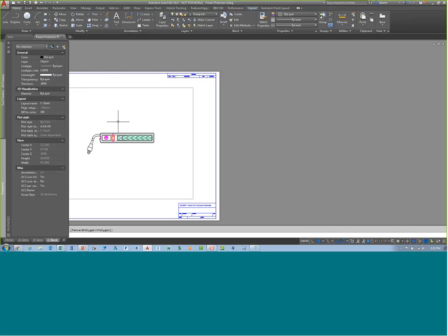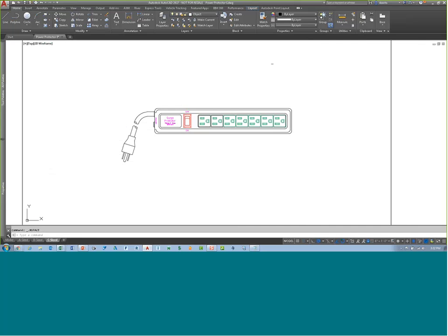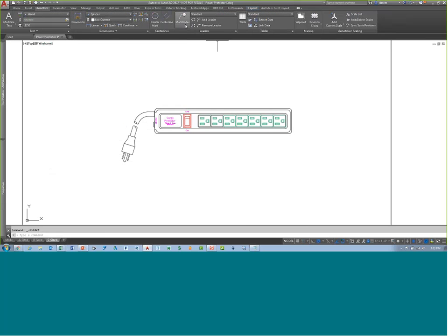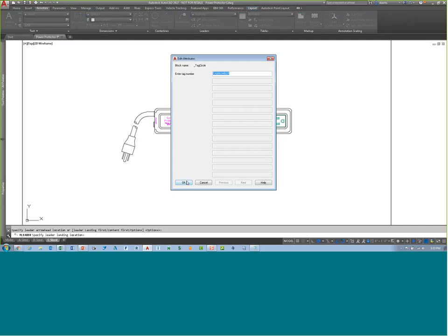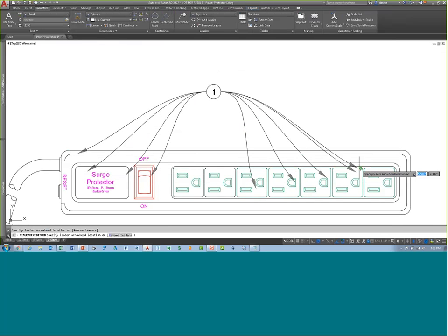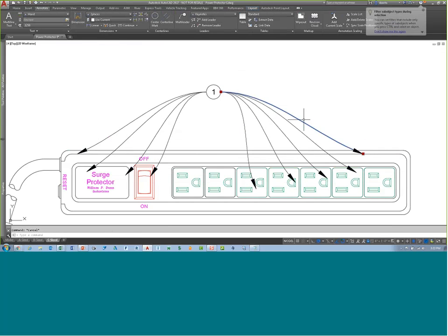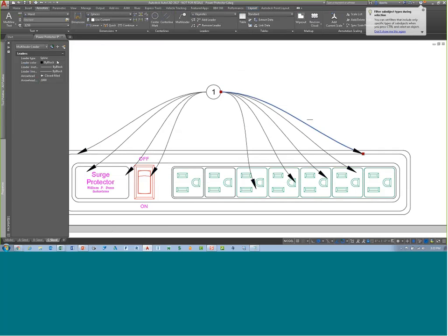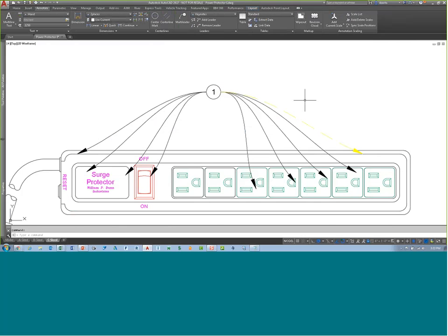Okay. So leaders. Creating leaders is not that hard. Annotate tab, leader commands. Pick the style that you want to work with. Hit multi-leader, and pick and go. Here's the thing, though. You can add leaders to this as quickly and easily as you want. You can also hold Control and pick a specific one, that subobject selection set, and switch its line style to something else or line thickness to something else, and even its color. Like that. I hope that answers your question about leaders, David.